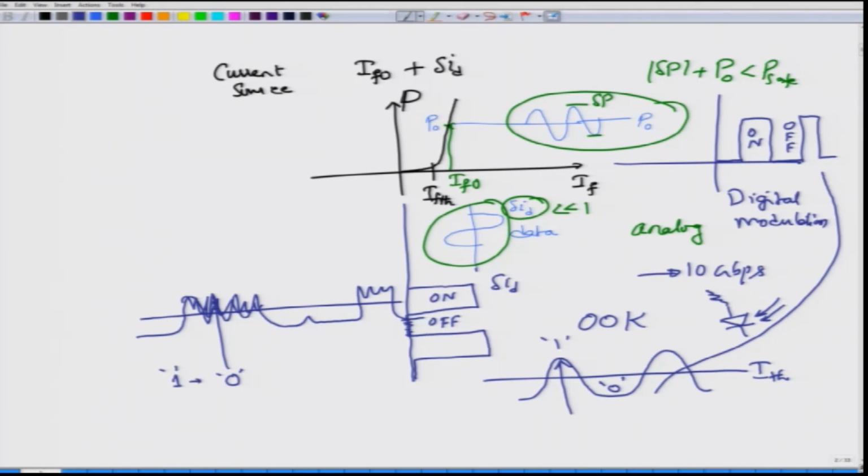of one kind. This is an error where you have transmitted 1, but you decoded the received symbol as 0. You will also make an error when you send transmission as 0, but the receiver receives this as 1, but this usually does not happen for a photodetector that is operating in the so called shot noise limit, which we have already discussed a little bit, shot noise and thermal noise, right, because shot noise depends on the optical power. It will be usually quite noisy for bit 1, and usually not much noisy except for the thermal noise in bit 0